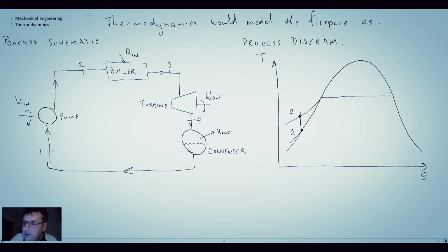And so what I'm doing is I'm drawing constant pressure lines on the TS diagram here. So this one may be 3 megapascals. I apologize, that's hard to read, the 3. Let me clean that up. So this could be 3 megapascals, and then this one here may be 100 kPa, so atmospheric pressure. So I'm going to draw arrows just to show the direction that we're going in.